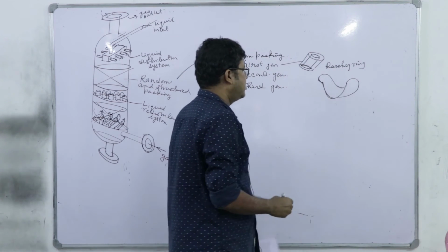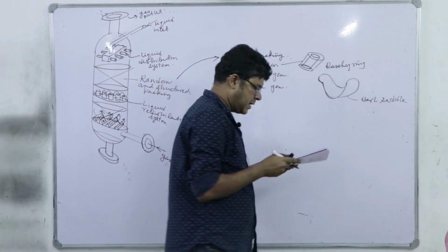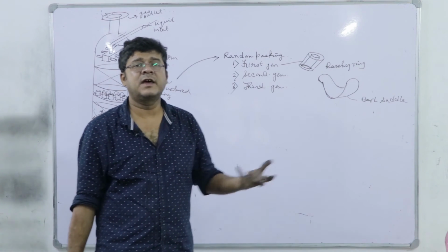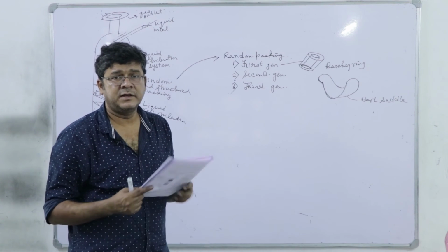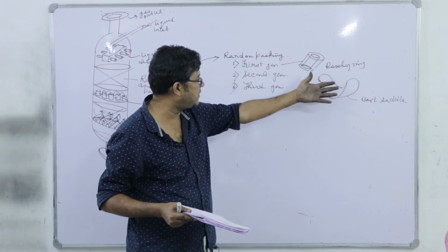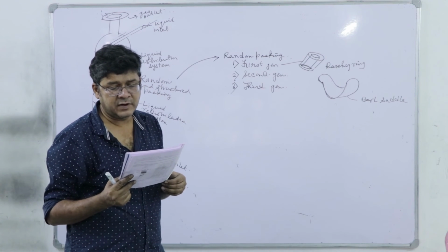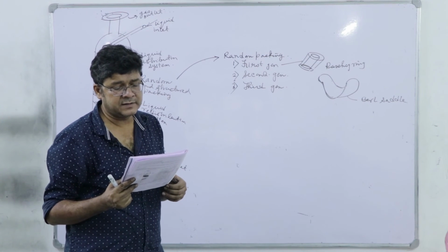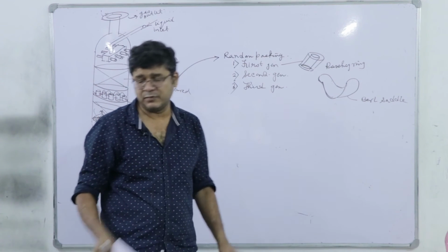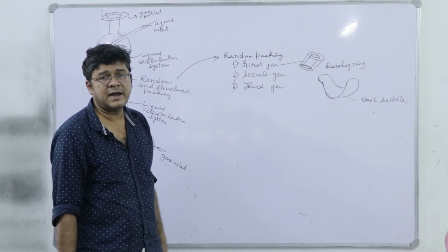This is a typical ball saddle. Right. And nowadays we have the flexibility of molding. The advantage in molding gives rise to different types of complex geometries in random packing design, and that is why the ball saddle and Raschig ring are first generation packing elements. We have second generations, third generations, etc. Second generations are the typical interlock saddle, then Nutter ring, Jaeger ring, Koch Flexi saddle. These are third generation packing. We do not have to remember these names, right? But just note the Raschig ring and ball saddle as typical examples of random packing material.